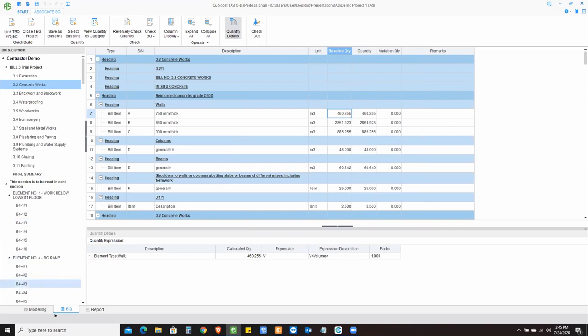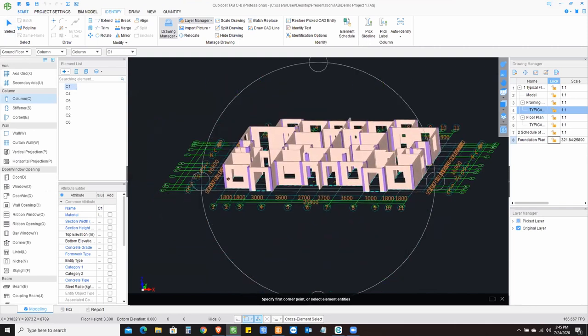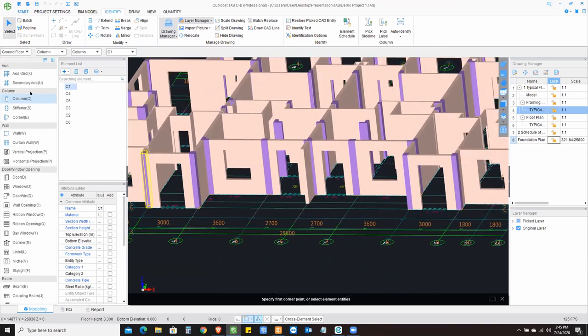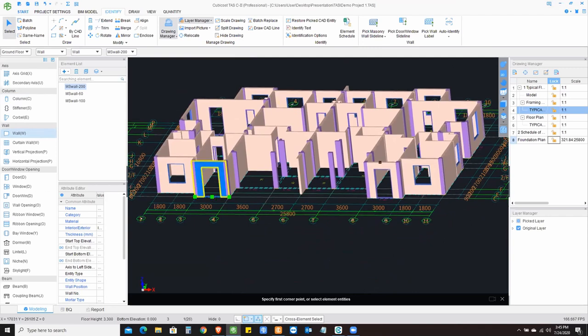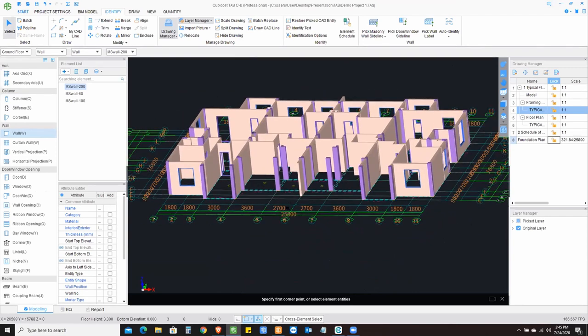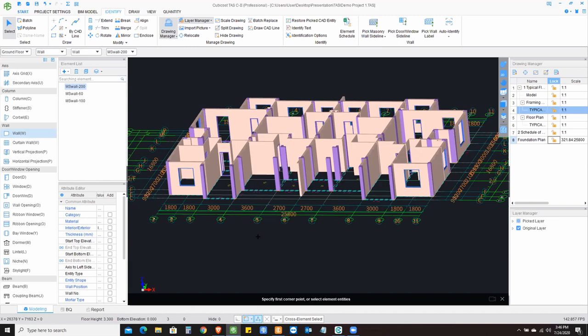And then if I go back to my model at the moment, and I say, okay, there are some modifications being made in the ground floor that we're working on. The client doesn't want this wall to be here. So I'm saying, okay, delete this wall, delete this wall. There are some modifications or changes made in the project. So all I need to do is, after that, just press calculate to run the calculation for this particular floor. And this will basically affect all the quantities throughout the linking BOQ, linking quantities, until the cost analysis.